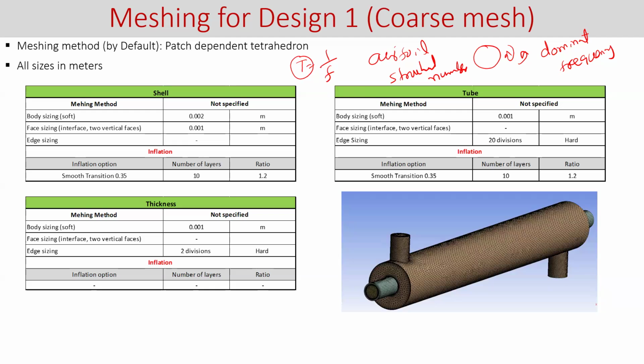The best way is, for example, if you want to learn how to calculate the time step, you go to that particular problem and find some papers or theses. From those papers, see which factor they use to determine the time spent for that particular flow. Once you get the time, dividing it into time steps is very easy. You can divide it into 40 steps, 100 steps, or 200 steps. Then maybe the question is, what should the value be?